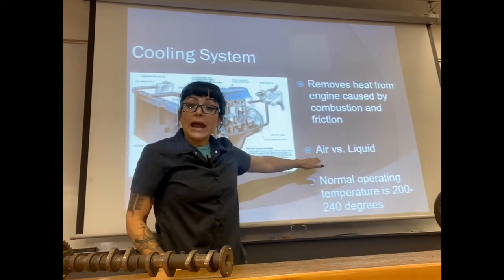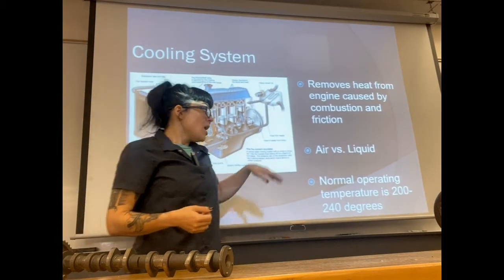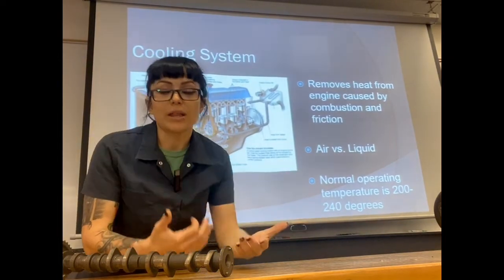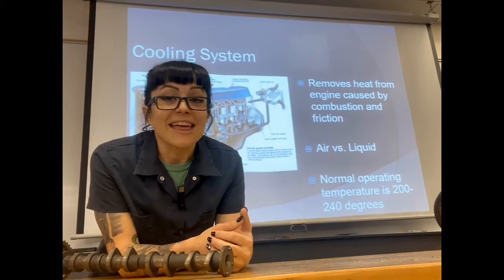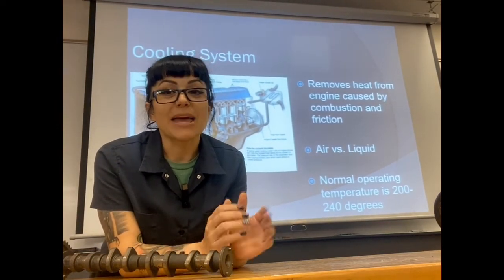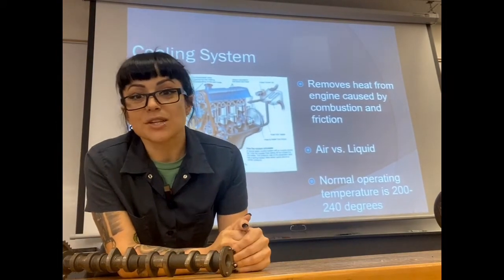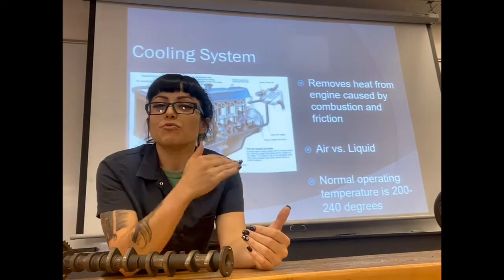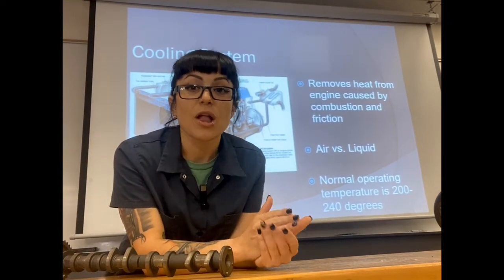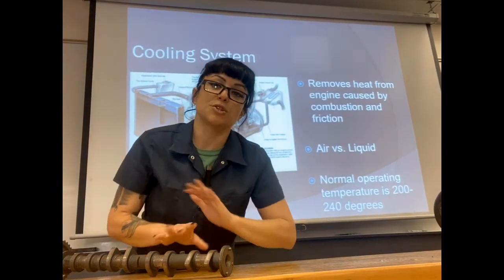Older engines are air-cooled, in some cases Volkswagen, Porsche, things like that. Oddly enough, you'd think that with air cooling they probably overheated a whole lot. They actually had a really hard time getting up to operating temperature, and they weren't running as warm as they should have been. That was actually one of the downfalls of the air-cooled engines. Liquid cooling helps regulate a whole lot better, and we'll get into that when we get into cooling systems in general, but that's why pretty much all vehicles across the board are liquid cooled and not air cooled. It helps with regulation a whole lot more.